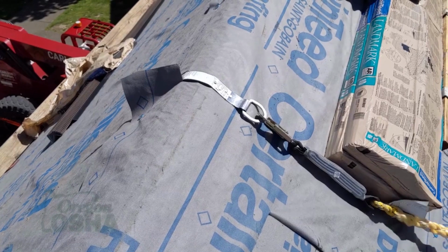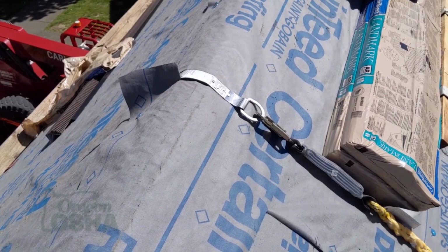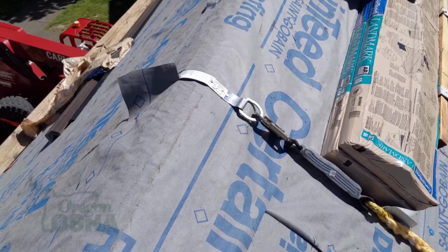So again, working in fall restraint really limits us, because it doesn't let you get very far before it stops you. And oftentimes we're laying out 10, 12, 20 feet ahead of us. And so having that fall arrest system adjusted to where at least the rope has stopped you from going beyond the edge, but that lanyard still does have that opportunity that you can fall off, but still catch you before you hit the ground. So one of the important things to keep in mind with fall restraint versus fall arrest with the 6-foot height is making sure that you limit yourself to just getting to the edge of the roof.